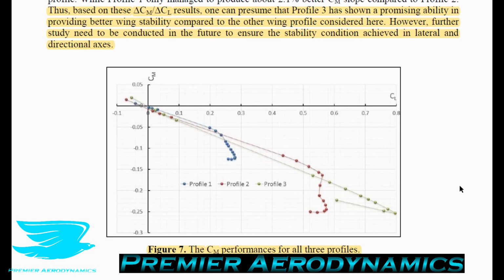You want to approach like 2 degrees, perhaps your cruise angle of attack. That's safe. If your moment coefficient compared to your lift coefficient, if you plot it, is a positive slope, it means that your airplane is unstable. Now for this,